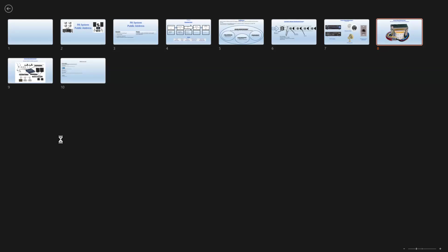So this way, you have an idea how commercial distributed audio works. It's also called a constant voltage system. And it's using transformers to talk to each other, so to speak, to work things out as far as the impedances and all that stuff. So we can just connect everything in parallel, just tap in, tap in, tap in, until we run out of power capability based on the tappings that we have used on our speaker stations. And that's how this is done. I will tell you more from the practical side during the lab, which I think is going to be tomorrow.